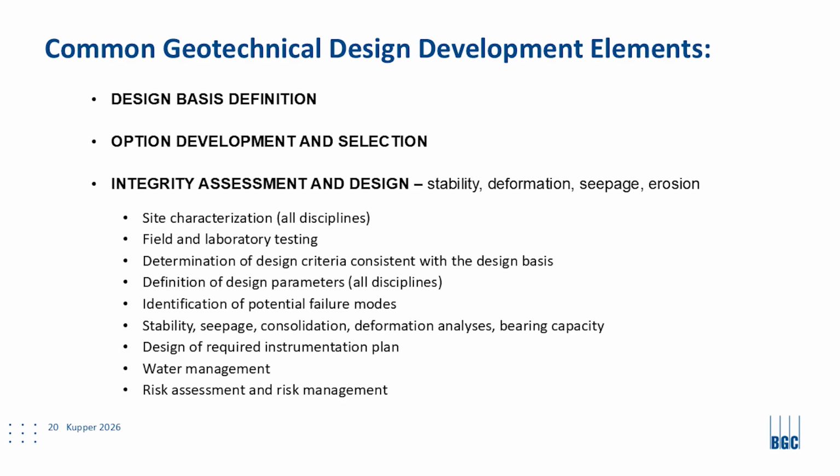You need to identify them first, before you get into the analysis, because it will affect how you set up your analysis. But then, by the time you plug in all the parameters in your analysis, you may learn something. Oh, the lowest factor of safety is not exactly where I thought. So you may have to go back.